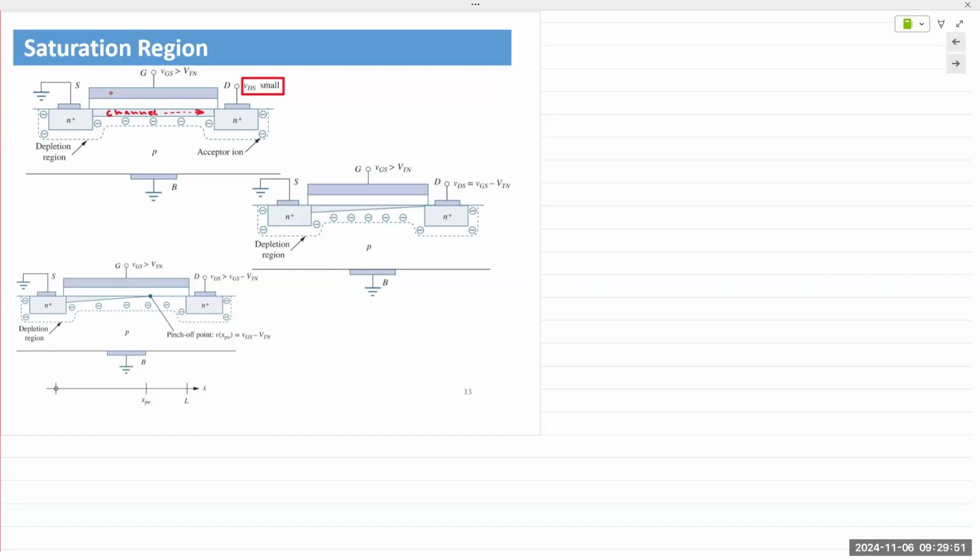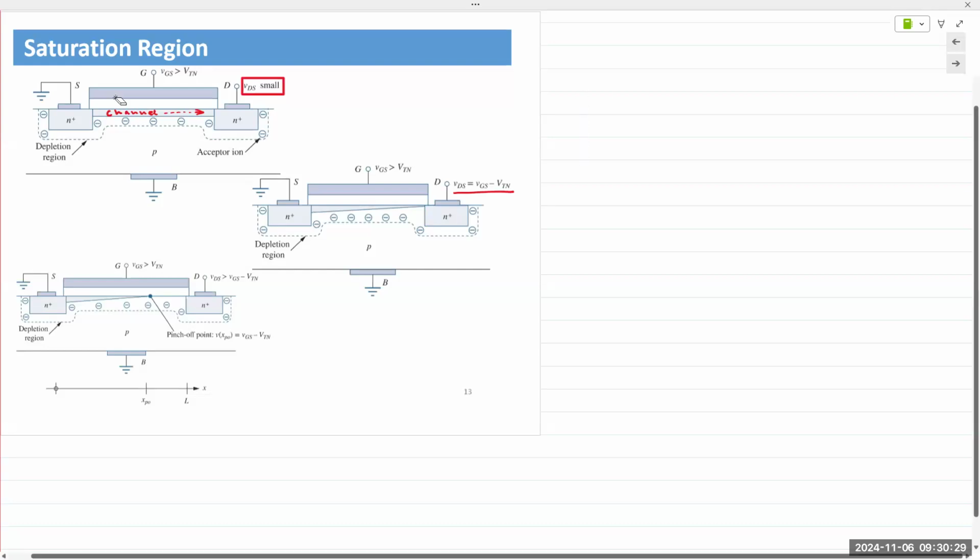Threshold voltage is the level of voltage that is required to just create the channel. That's VTN. That's basically the inversion process. So threshold voltage is the voltage where the inversion happens, and then VGS is at a higher level. So when VDS reaches the level where it equals the difference of VGS and the threshold voltage, a voltage exists between the drain and the gate.